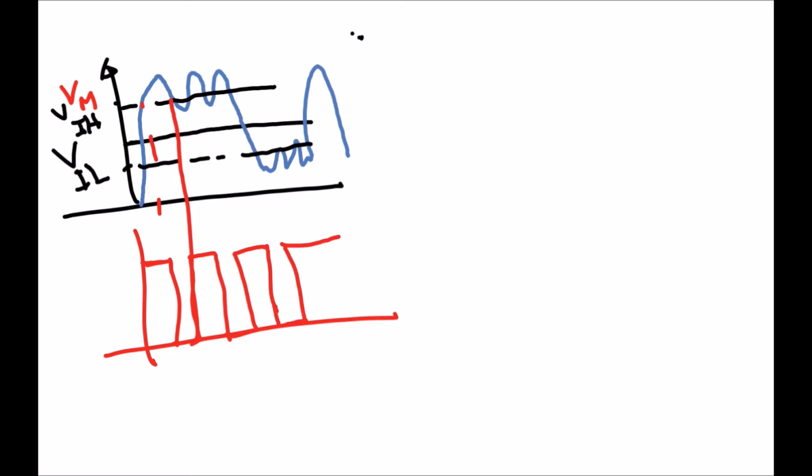What happens with a Schmitt trigger? A Schmitt trigger is triggered only in one direction, which means it will start normally here with high, and then it goes to low, but it will stay low. It will not change its state, because there is a difference between V input high and V input low, or what we call here V switching point high and switching point low.